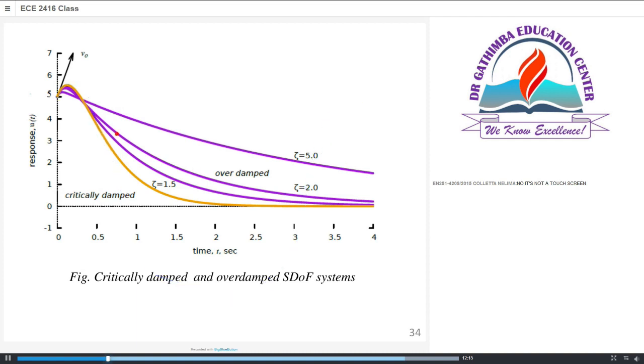But with the damping, if C is equal to the critical value, or even greater than the critical value, then the motion is not periodic and is not oscillatory. And here we are giving different values. So the behavior is almost the same, but depending on the value of the damping coefficient, we are going to see what this value means.